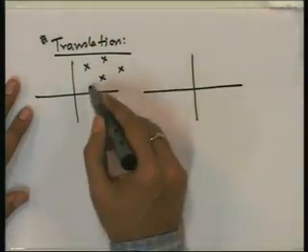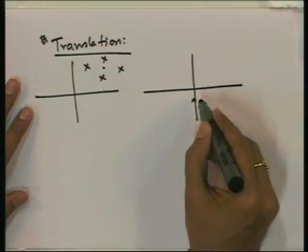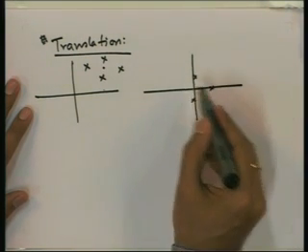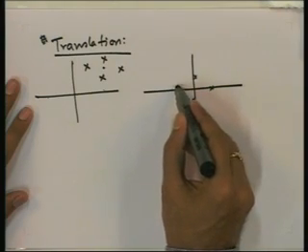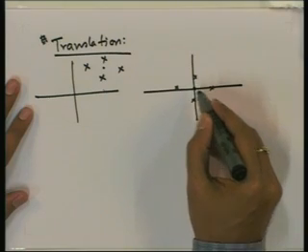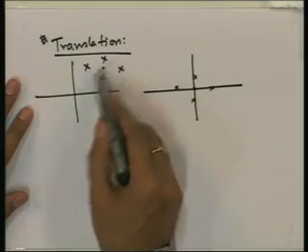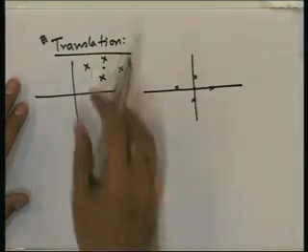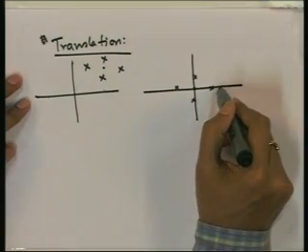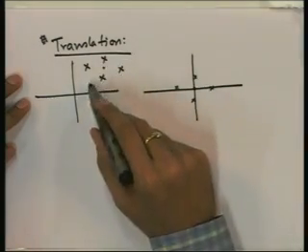By translating each point by the same number, we can bring this point to 0, and then this signal set would look like this. Now the center is here. So, we can intuitively feel that the energy of each signal is reduced here, because they are brought nearer to 0. As a result, the average energy transmitted using this signal set will be less than the average energy that is used to transmit the original signal set.